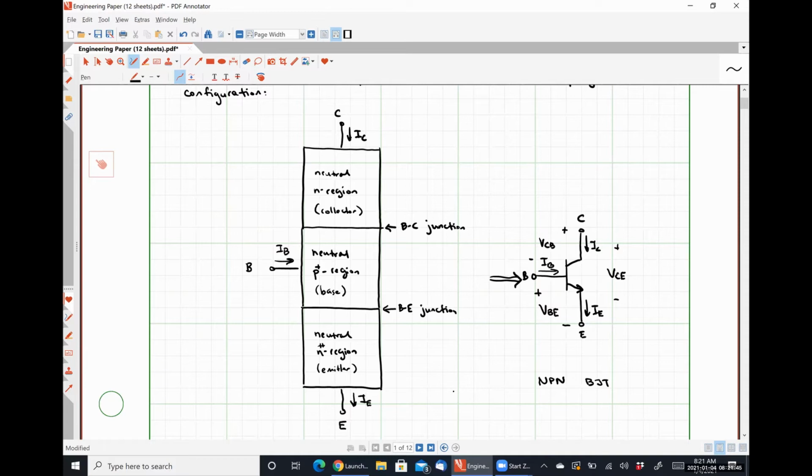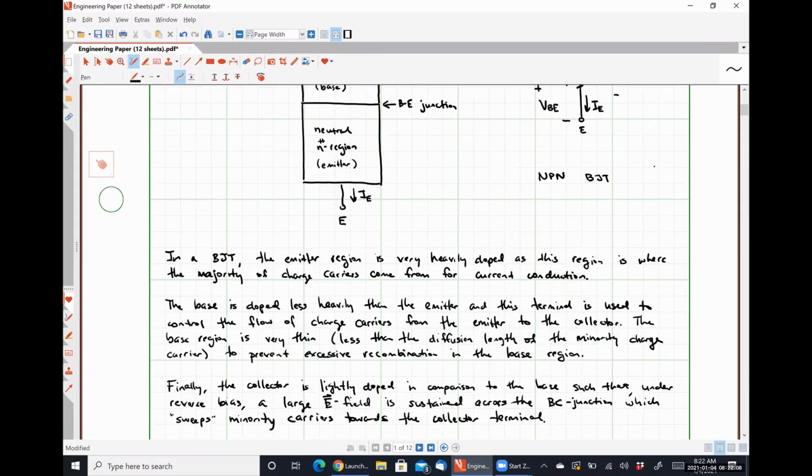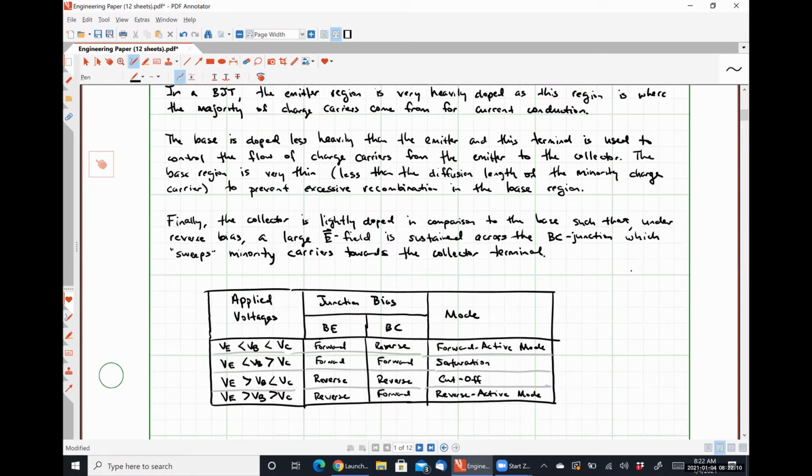This is why, because it's an asymmetrical device. So you can still get those same currents out of it, but because it's trying to pull more electrons than can be supplied, the temperature has to increase in order to thermally generate those electrons. Causes it to run really, really hot. So we're going to focus today on forward active with the understanding that reverse active is effectively the same thing. It just does it more poorly. All right.